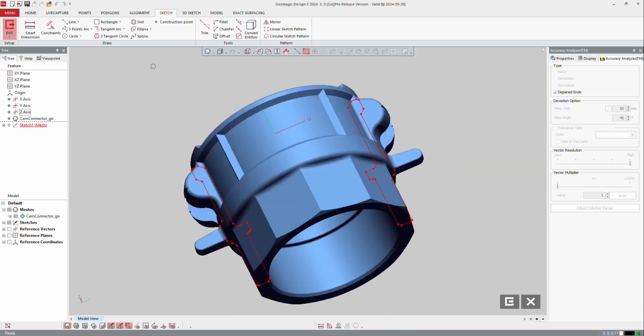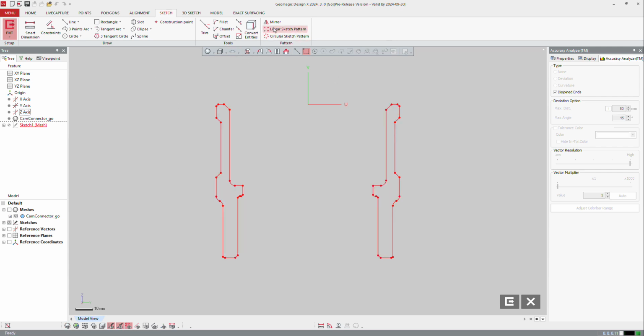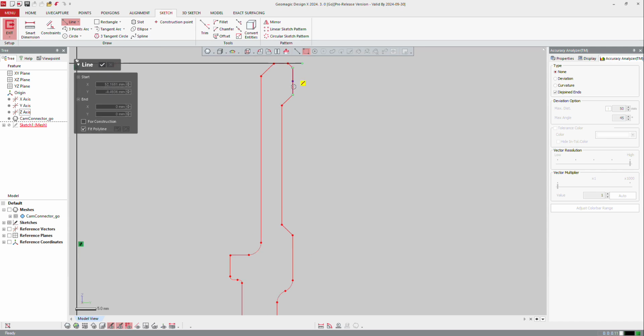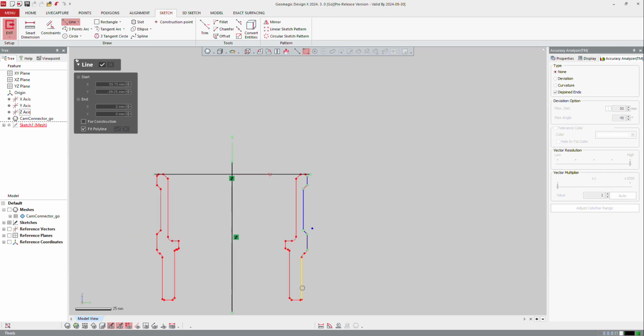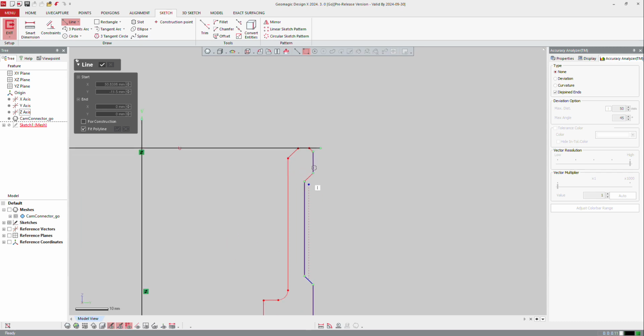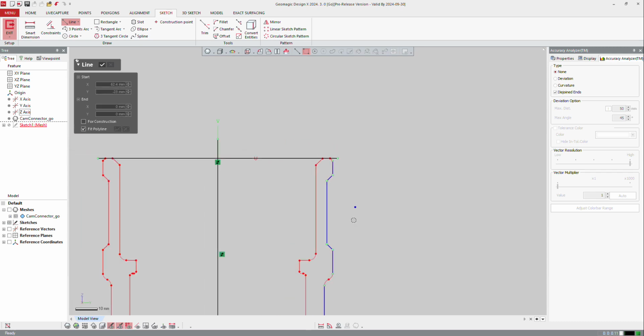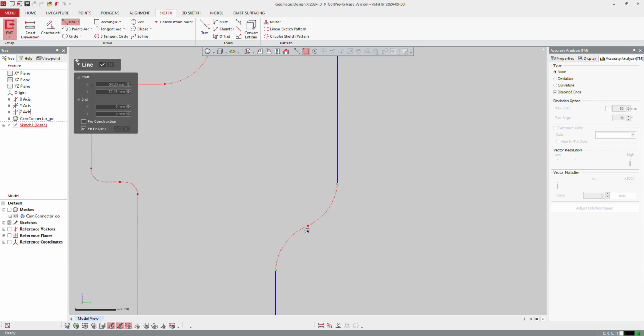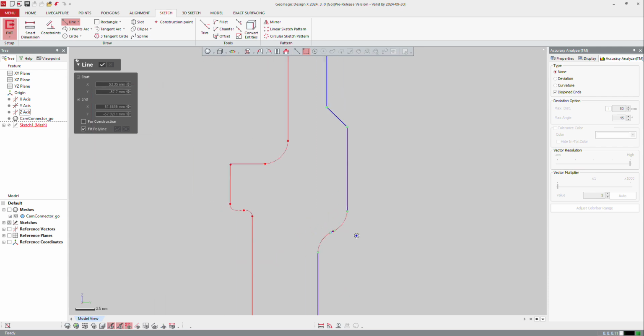Okay. Now I will create my sketch, but first of all, I can retrieve the Y axis and the Z axis, as this is a revolution axis, and these can be used on the part. From that, I will now build my sketch, so I can double click here, double click there, and create all my curves or lines on the part. Don't forget, I can also create extra lines like that one between the two fillets. There is no line, so I will create that line.